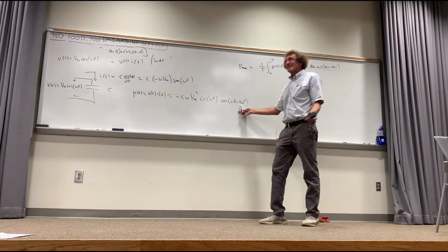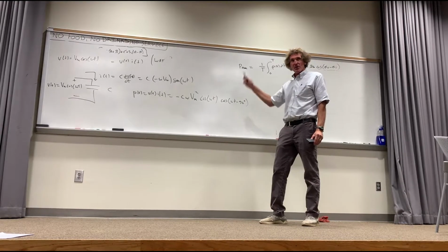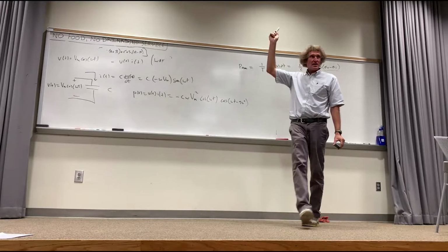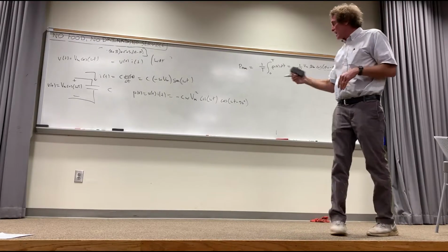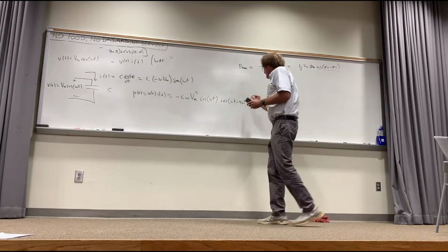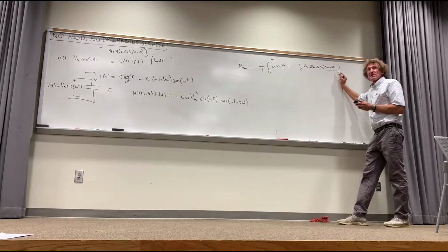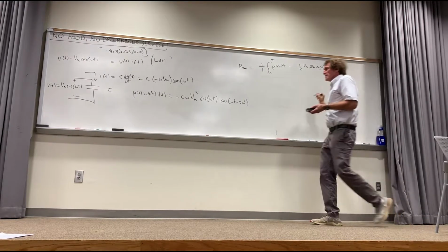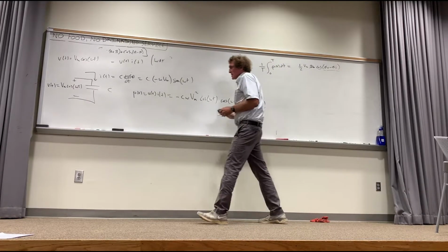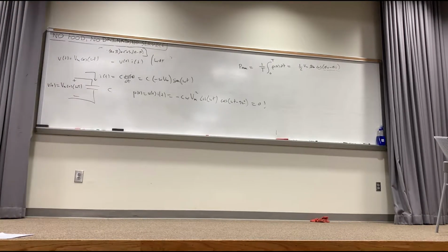If you have two waveforms that are 90 degrees out of phase with each other, and you integrate those things over a period, you get 0. How many know that? You integrate a cosine theta times the sine of theta from 0 to 2 pi radians, you get 0. I can prove that, but the real thing is this. It's the angular difference between the argument here and here that you have to get, and then the cosine of that. The cosine of 90 is what, class? 0, right. My point is this. The average power dissipated by a capacitor is 0. Everybody follow me on that? You can mathematically prove it.